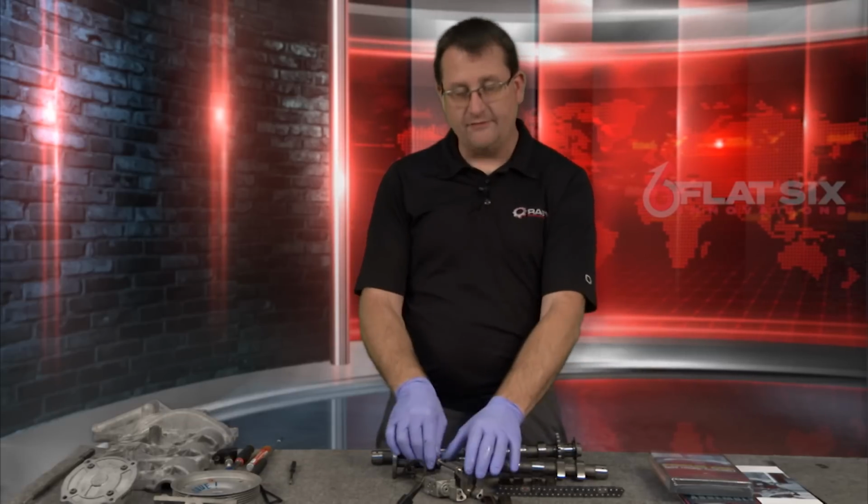You just want to put enough tension on them so they're not going to flop around and try to fall apart. If you leave this completely compressed, it ends up being kind of a cluster when you go to put it on the engine because they want to jump out of the chain links and all that sort of thing. So back it off just enough that you don't have a problem with the unit trying to stay together, okay?